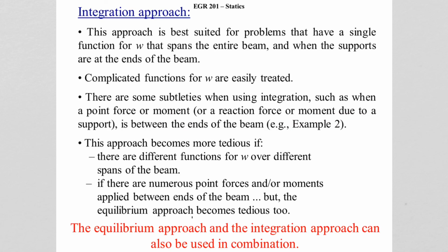This approach becomes more tedious, again, if there are more different functions of w as it spans the beam, and if there are numerous point forces. So they both can become tedious at different times. The integration approach and the equilibrium approach can also be used in combination with each other.